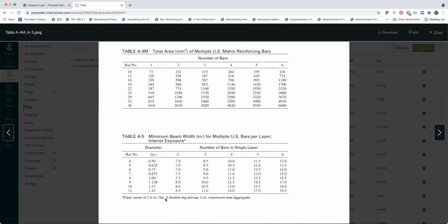If it's not, you cannot use it. And it has to be 3/4 aggregate size maximum. That maximum can be lower than this, but cannot be bigger than this. If you have aggregates of 1 inch or anything above this number, you cannot use this table. So this table is only convenient when you have all these conditions met.